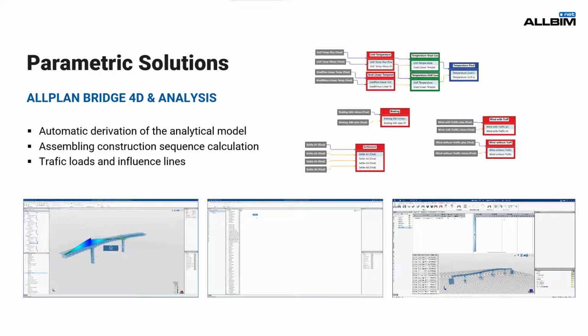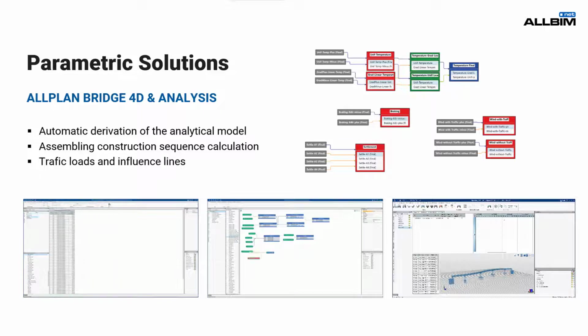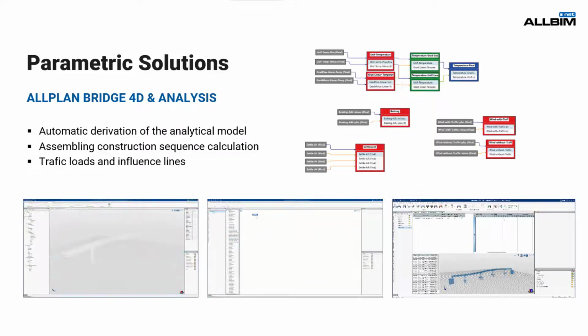The definition and visualization of combinations in table form provides the user with an overview of not only the defined load factors, but also the various types of combinations. By simply specifying the construction process, time as a fourth dimension is taken into account. The construction plan can also be divided into phases, which are further subdivided into individual tasks.